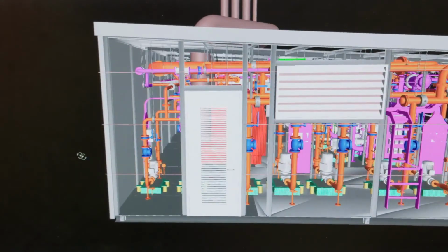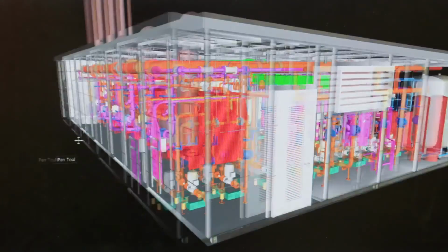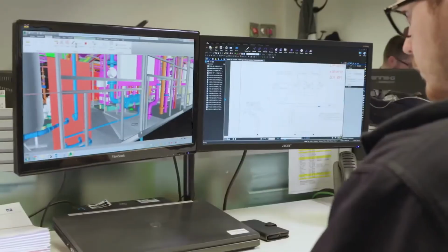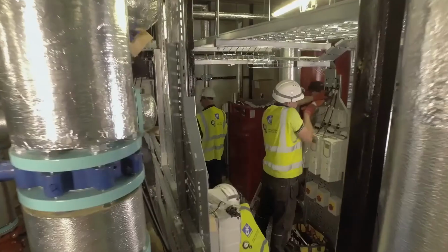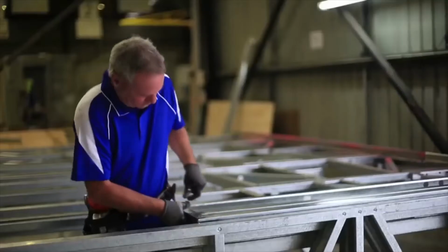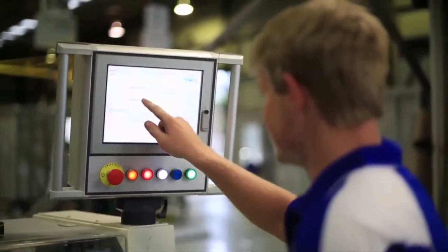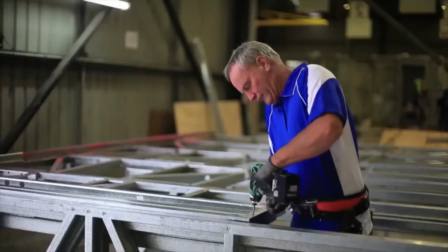Off-site manufacturing processes are supported by the use of IT tools and building information modelling. BIM tools can provide manufacturing data files extracted from the design model to be used directly in semi-automated production equipment. Multi-skilling of factory operatives in the off-site environment facilitates the integration of job roles and promotes a more collaborative approach. The manufacturing process needs to be in sequence. In some scenarios, manufacturing may be undertaken near site to facilitate improved logistics, often referred to as flying factories.